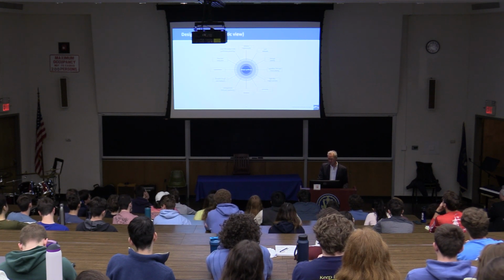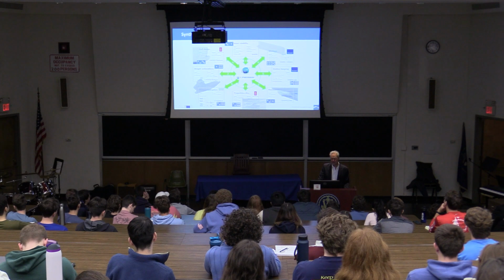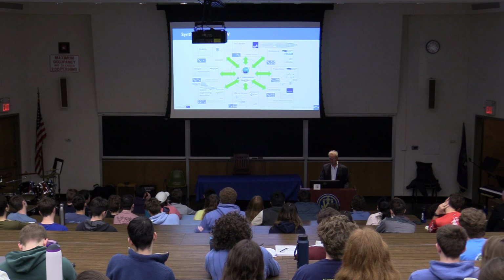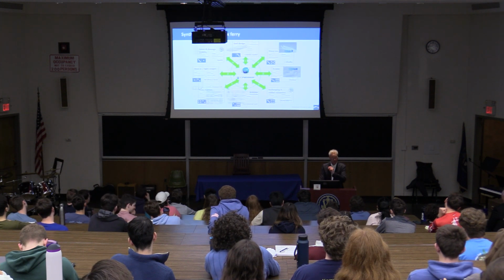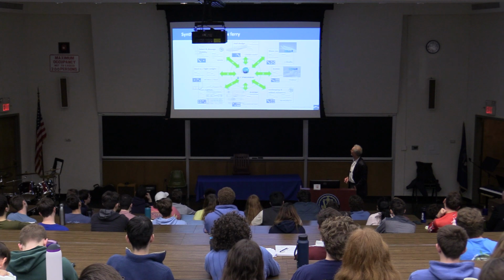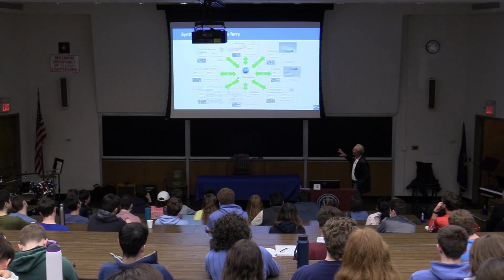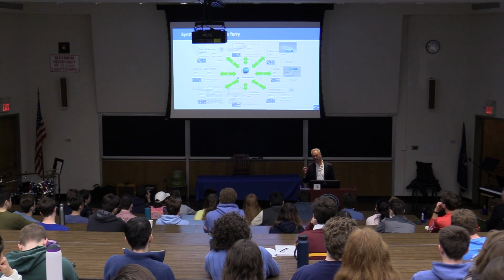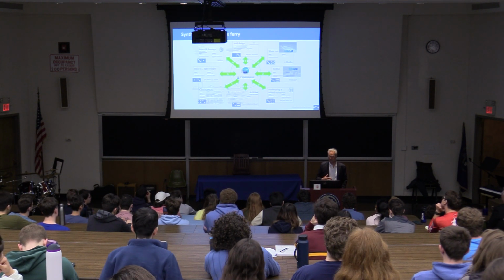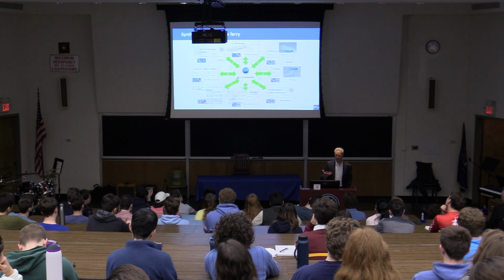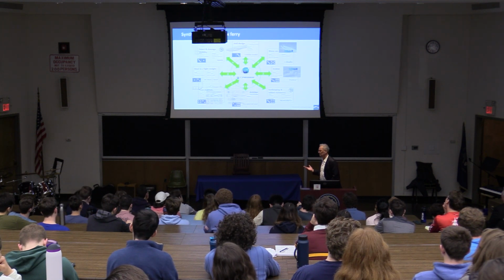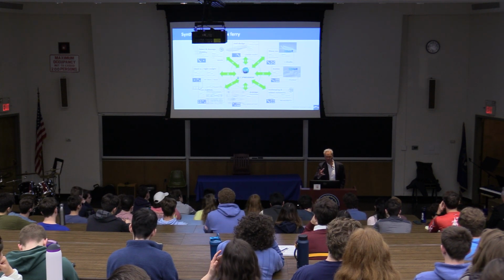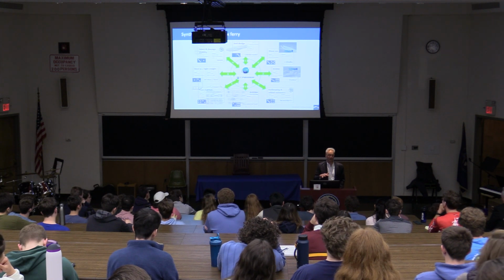We call them synthesis models. I'll show you a few synthesis models just so that you see they all look different and all complicated. But what I wanted to bring home in the last 2 or 3 minutes is, if you have many things to look into, why not produce your own numerical series up front? You might just say, okay, I'll produce a hull form and I'll run 500 CFD runs up front, so that I would have an idea, for instance, on the resistance and on the thrust for different geometries.